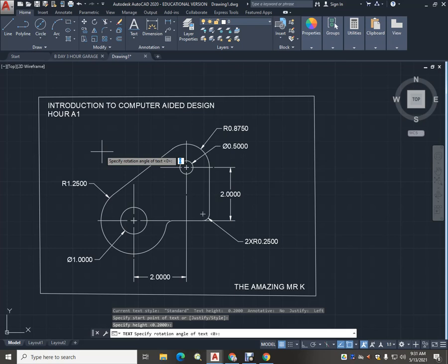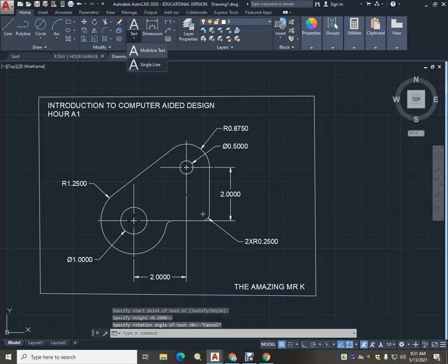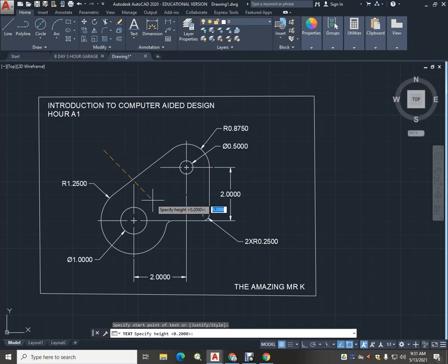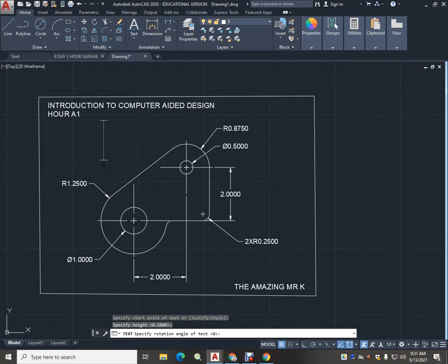Now some of you folks, here let me just show you something. When you hit this thing, you've been running it down like this. And what that does is the text height is the same, but if I click here, again, notice that even though it said 0.2, when you moved it like that, it's gonna try to type really big.